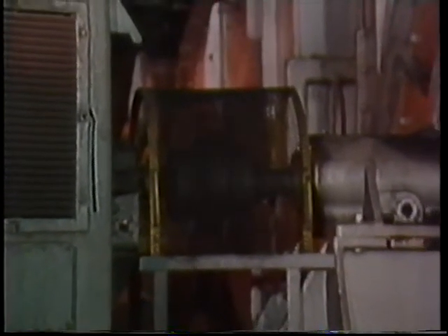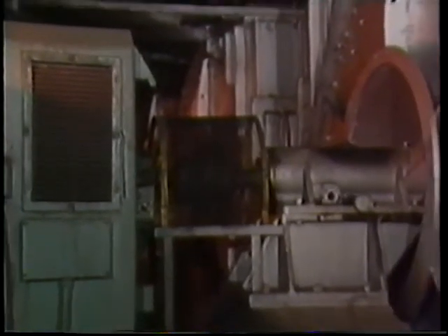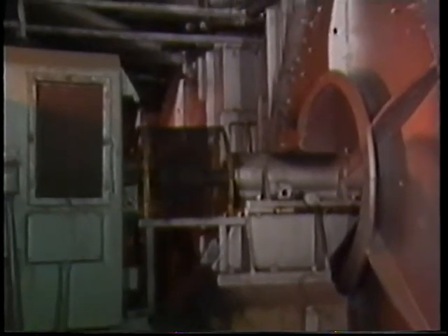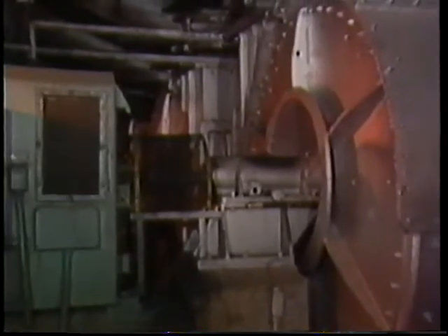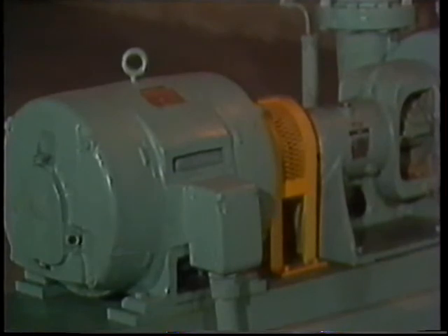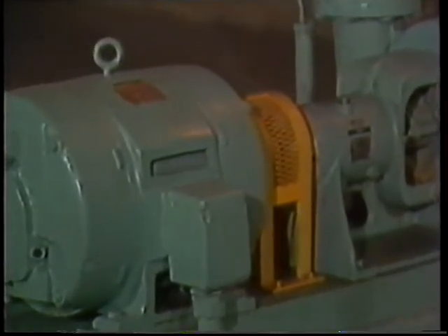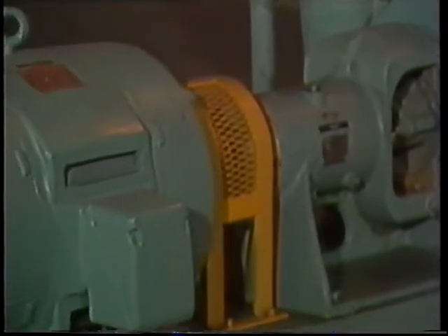Vibration is simply motion, movement back and forth or up and down. As the operating condition of the equipment changes, the associated vibration can change in direction, and it can change in amount. For example, as a bearing wears, you should expect the amount of vibration to increase. This is a normal occurrence when the machine's rotating parts start to wear. By monitoring the amount of vibration over time, you could determine when the bearing would need to be replaced.